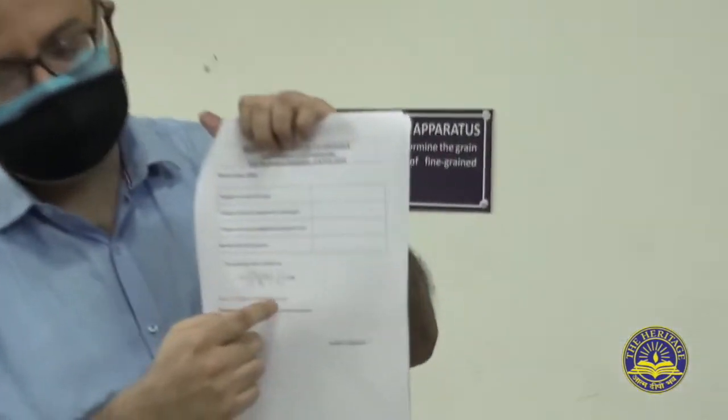Next is the shrinkage limit. Now what is shrinkage limit? Shrinkage limit is that limit where there is no change in volume of the soil. So volume of the soil will become constant. So how to determine the shrinkage limit? First you saturate the soil so that there is no void space remaining. And after saturation you put it in the oven for 24 hours. So it will be a dry soil pad, and after taking the soil pad, we have to use this expression to calculate the shrinkage limit.